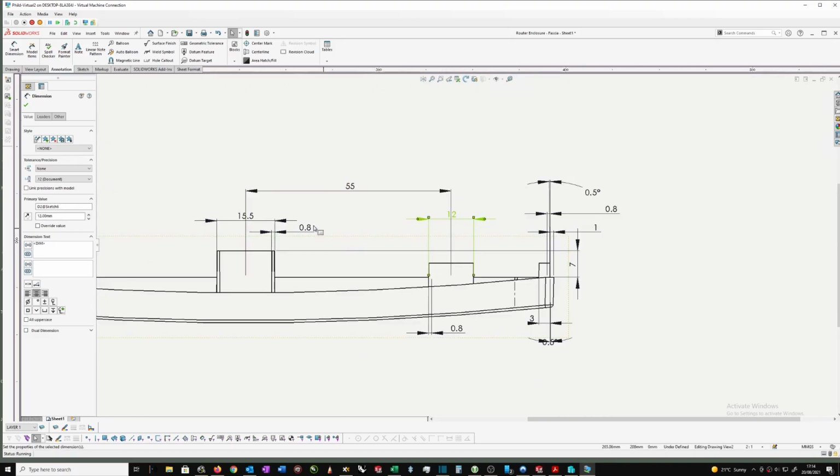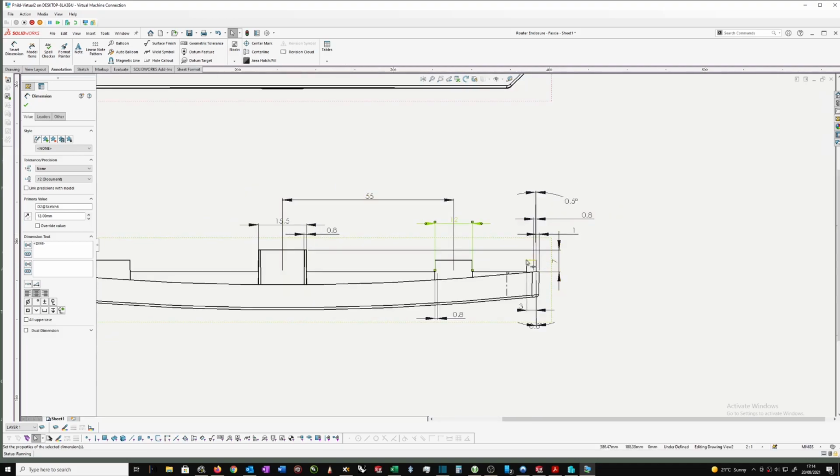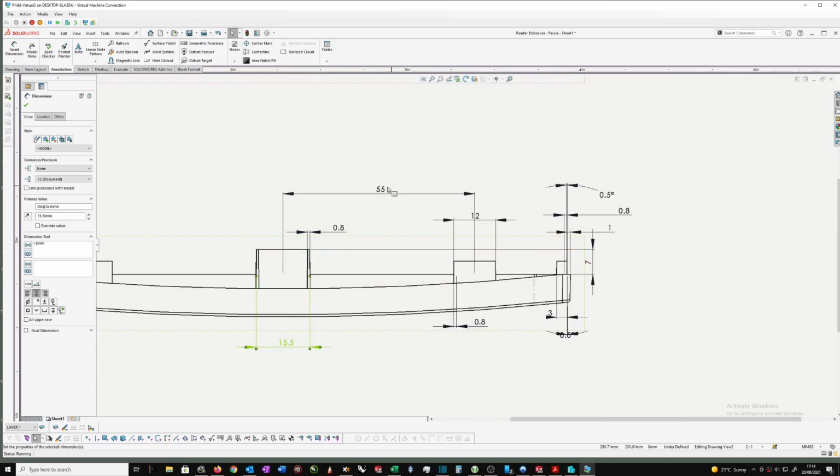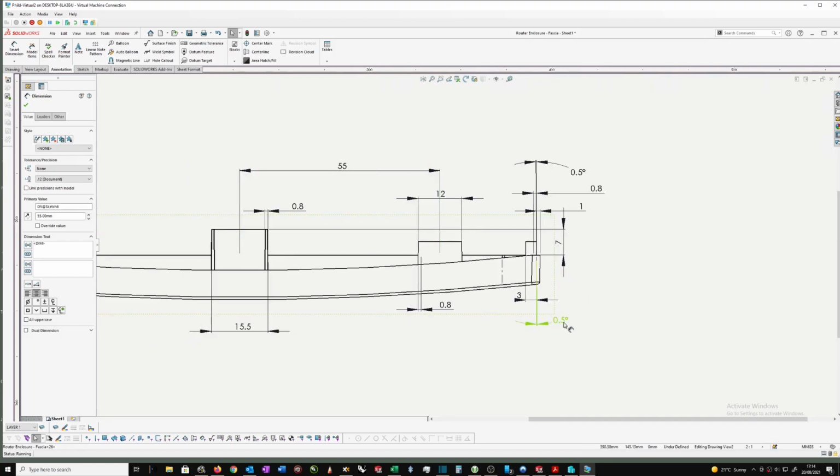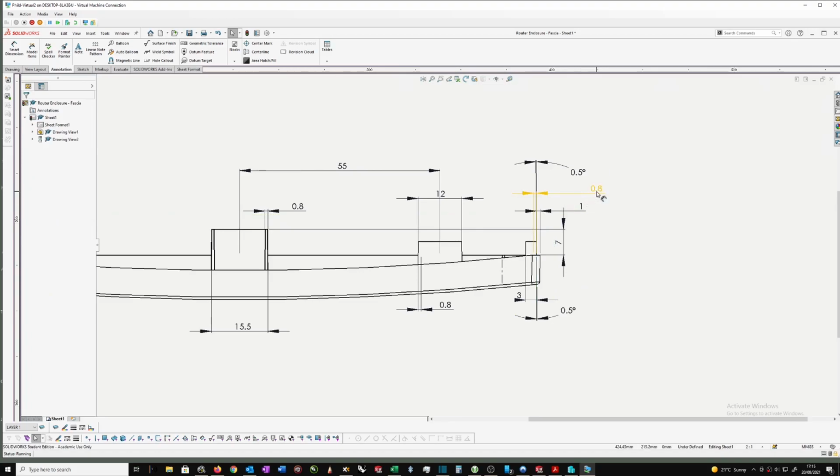If you bring something in, especially when it's got to do with complex parts, make sure that it's doing what you want it to do. Make sure it's dimensioning anything useful, and especially that you don't have dimensions pointing to the middle of nowhere and not telling you anything whatsoever. If you do that in your drawings, I'm going to mark you down. So please be careful of that.